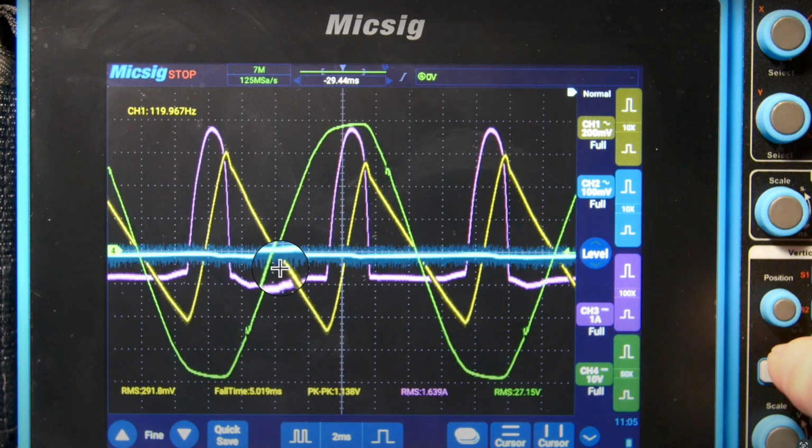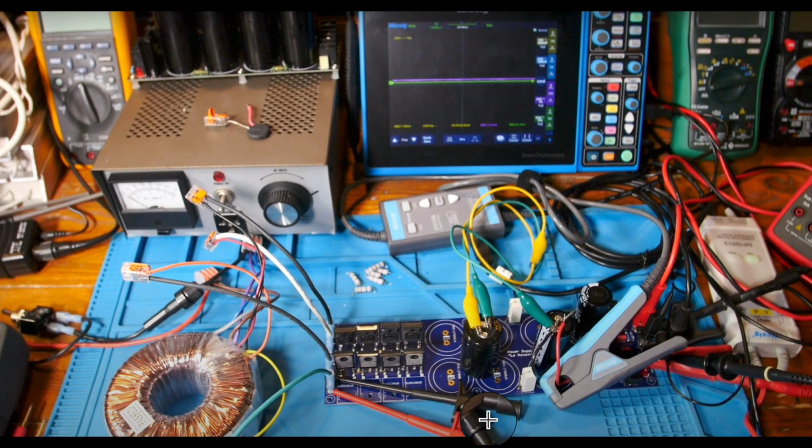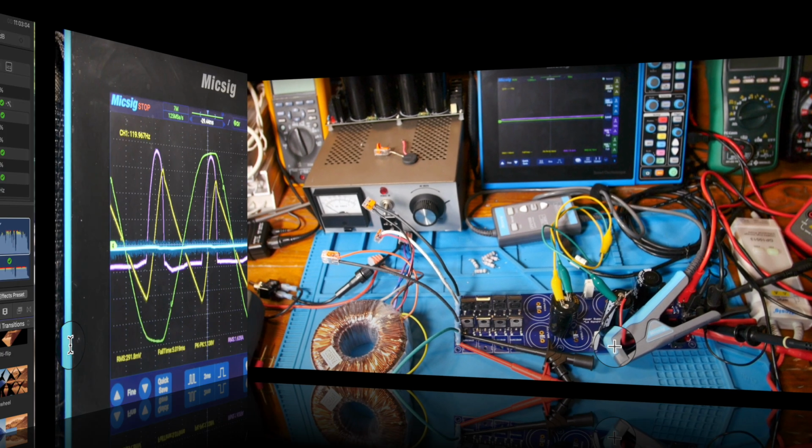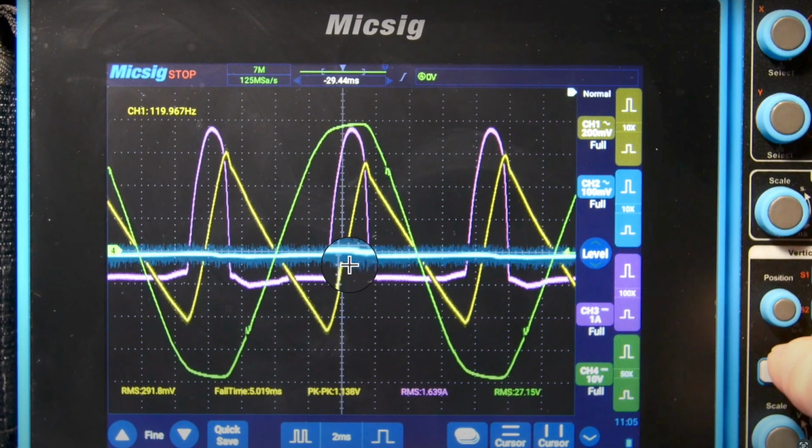Well, now it makes me want to go back and look at that picture. All right, so see where the current clamp is? The current clamp is on this wire going to the capacitor. So the current coming from this board is coming through the board down here, and then it's going to go out here to the output. So there's 1 amp going this way. So we're not really seeing that 1 amp. All we're seeing is the current going into and out of the capacitor. Yeah, this pulse of current is only going to the capacitor, and the pulse of current is going out of the capacitor.